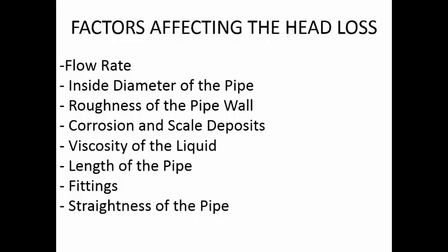So once you have a proper design, you have to go for the selection of the pump and the selection of the motor. That is the important thing. If you want to have a pump, you have to always know that the pump is designed to deliver the fluid at the required pressure. Whatever pressure the pump is able to create, it should be more than the pressure which the actuator needs. Why should it be more? Because there are going to be losses as the fluid is flowing through the system. So all the losses have to be overcome, and when the fluid reaches the actuator, it should have the required amount of energy. Then only you are able to get the required kind of output.